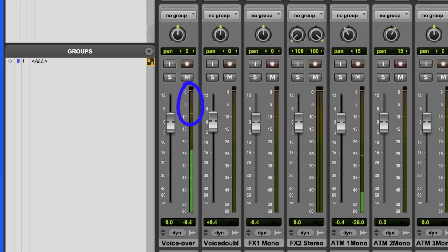It's advisable to leave at least 8 to 10 dB of headroom between the signal peaks and the maximum 0 dB full scale. When recording speech, this means that the average level will be around minus 20 dB. For more dynamic sources, set the average a little lower and keep your eyes on the peak to allow 8 to 10 dB of headroom.